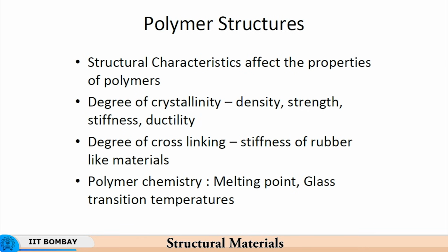Okay, ordered arrangement of atoms is the one that gives polymer the crystallinity, and therefore more is the ordered arrangement, naturally more is the strength of the polymer. Amorphous polymer will have relatively lesser strength and therefore a low melting point, whereas a polymer structure with higher value of crystallinity, meaning larger range of order, will mean that it will have a greater strength and greater melting point as well.